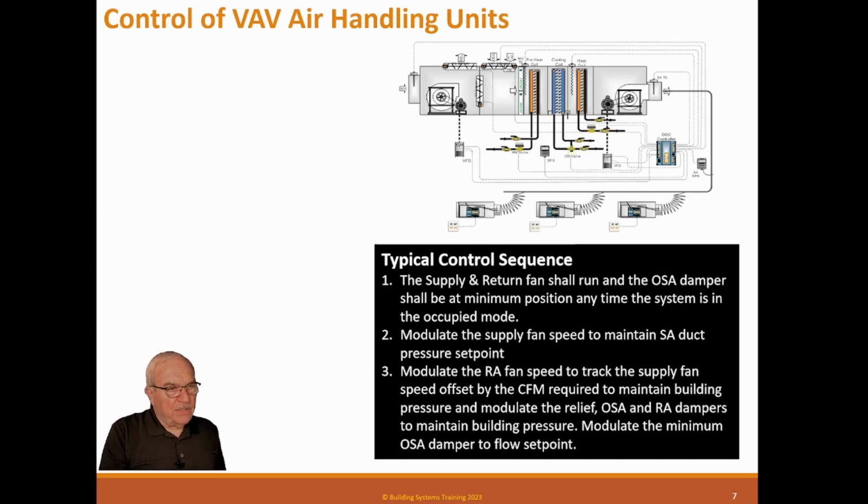Now remember, these sequences I'm showing you are what we call regular sequences that you might see on the drawing from the engineer. These are not actually programmed control sequences. A control programmer will have to have a much more complicated sequence. You might have timers in there. You'll have resets in there. You have a lot of things I'm not showing you because this sequence is just trying to tell you basically how the system operates. So there are courses coming that will deal with the exact sequences, but this one is not. This is just a typical sequence.